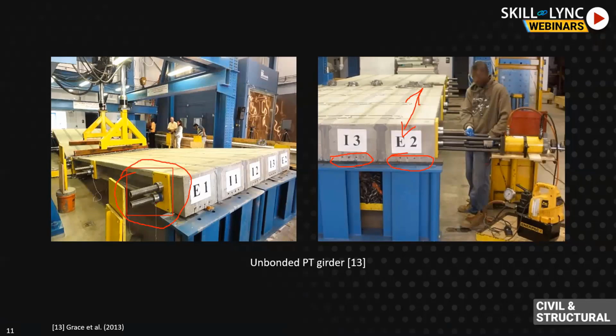So what we do here is we put a duct here, or probably this threaded rod, and we put all these things in before we start applying the load. And then we screw these threads and apply our intended force. Again, we can control it using load cells. We can control it using strain gauges, and we can see what amount of force we are applying, both in longitudinal and transverse direction.